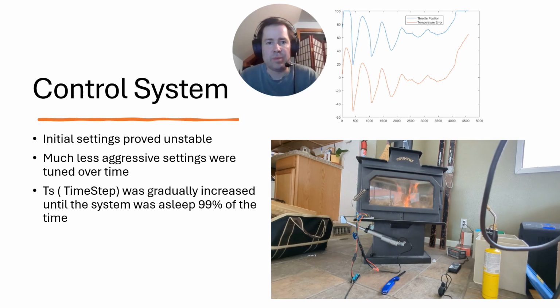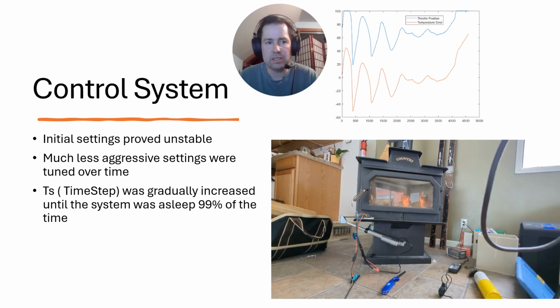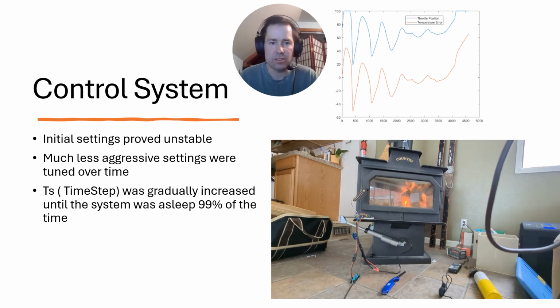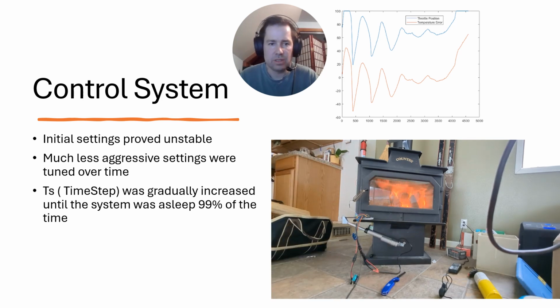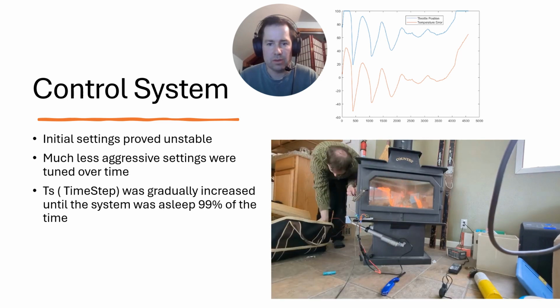So the first experimental runs were not very successful. Each time I would load wood, the system would go unstable. The system proved to be underdamped and had serious thermal swings. This caused the linear actuator to be in constant motion, draining energy from the system. It was failing to stay under 5 watts, so my system was constantly losing power, even with the stove at full temperature.